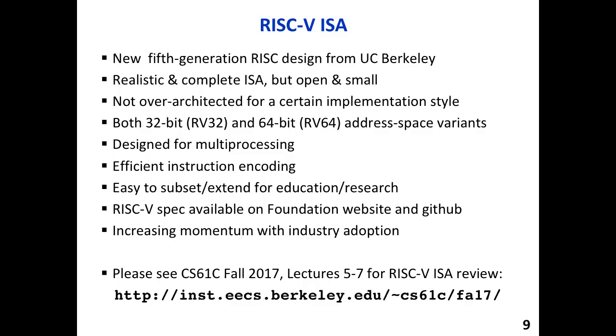Now, if we wanted to do that today, Altera supports a RISC instruction set-based processor called Nios, which allows us to do hardware-software co-design. But we don't normally reprogram Nios's instruction set.